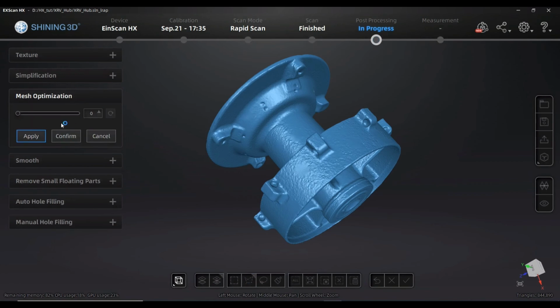Mesh optimization is something not too much described in the software, but I'm expecting it's doing what most similar algorithms do. That means there will be eliminated needle triangles, that means triangles that are very long and very thin. There will be avoided tunnels, or, let's say, inverted mesh areas and so on.